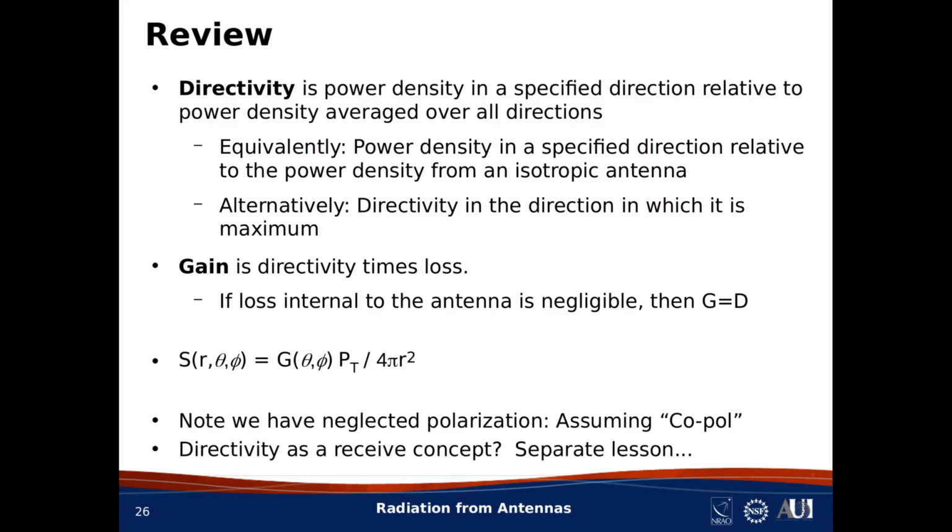And to wrap up, 2 additional comments. First, note that we have completely ignored the issue of polarization. In other words, we've assumed that whatever device is measuring the power density is copolarized with the wave. To the extent that this might not be true, well then of course the relevant measured power density will be less. Finally, perhaps you already know that the directivity of an antenna can also be used as a metric of receive performance. This is true, but a discussion of that idea will have to wait for another lesson.